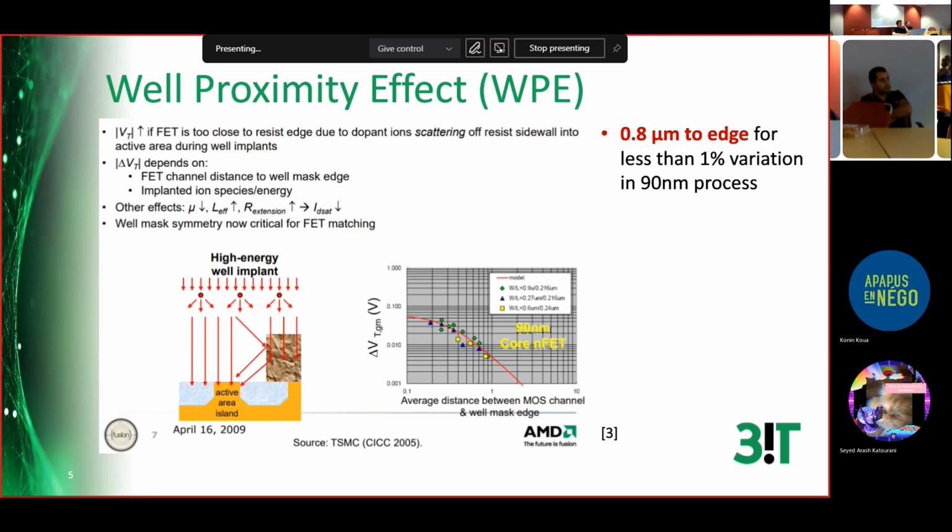This needs to be filled for uniformity, because you can also have some mismatch because of non-uniform exposure of the base layer or metal layer. I don't know if you already made the top design part, but usually at the end, before taping out, there is a fill script.